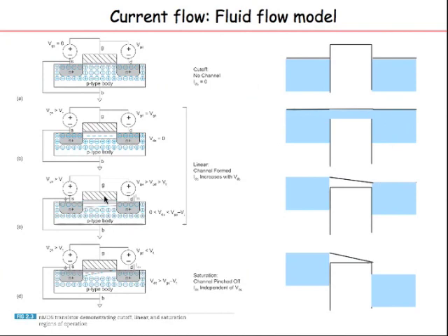What is interesting is that for a particular potential of the gate, where this barrier has come down to a specific location, as I change the potential of the drain and make it more and more positive, in this case I make the reservoir lower and lower. There comes a point, see here what happens as I make the heights of the two reservoirs different: there is a gradient.